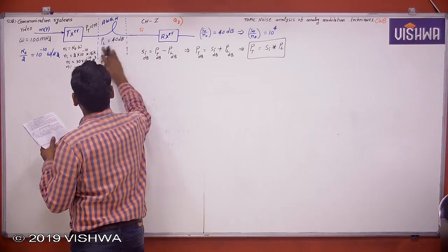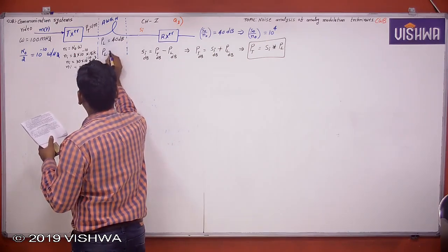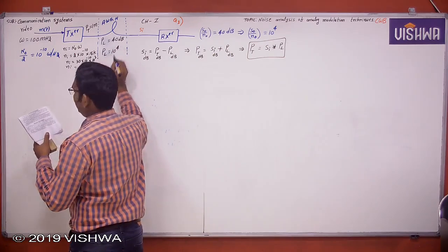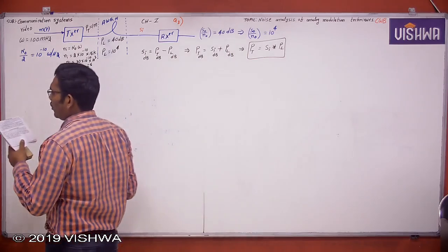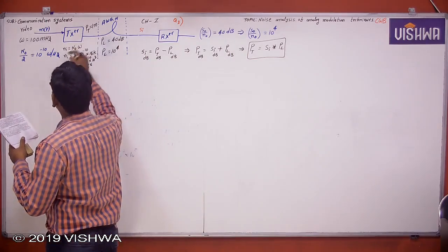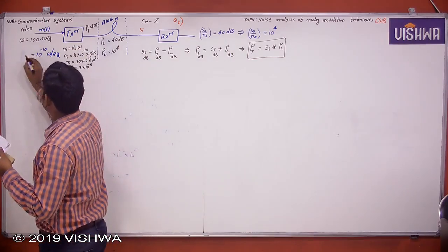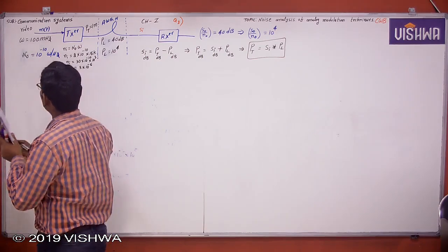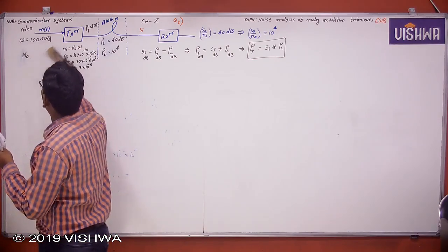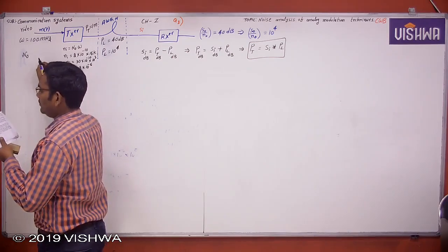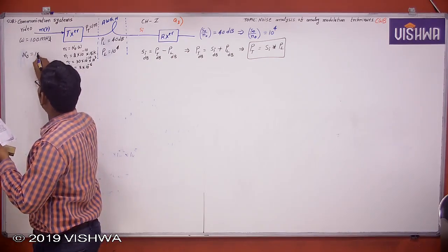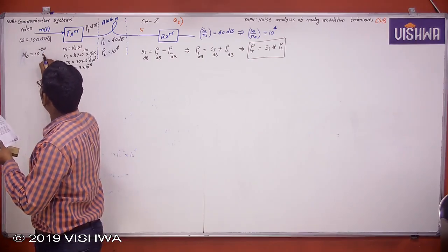Therefore, in terms of magnitude, this is 10 power 4. And the cable is affected by noise. What is the one-sided power spectral density? One-sided power spectral density means only N0. One-sided power spectral density is N0, which is equal to 10 power minus 20 watts per Hz.